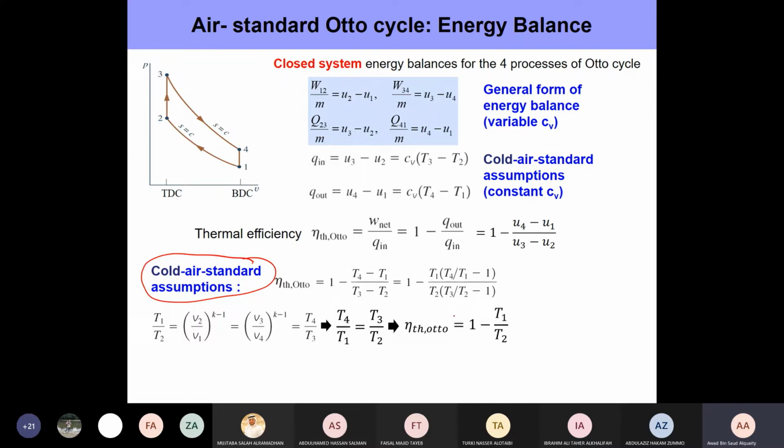And in some ways it resembles the Carnot efficiency formula. Now T1 and T2 are not always known. I mean, you can always calculate them, but these are not values which are given by engine manufacturers, right? On the other hand, what engine manufacturers like to mention is the compression ratio r, which is simply V1 by V2.